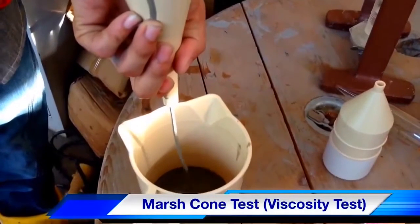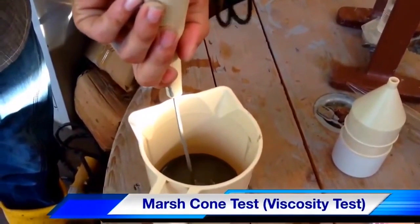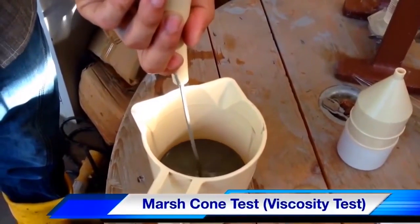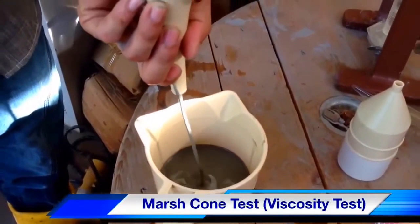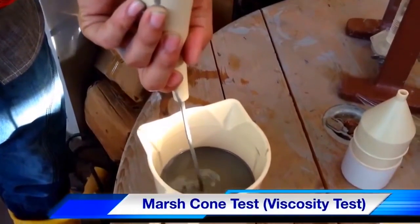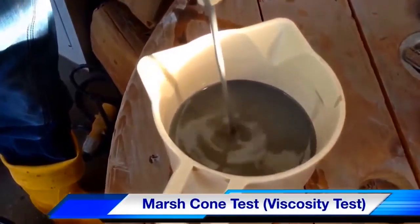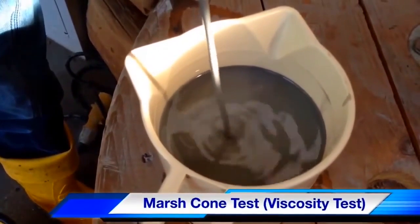Marsh cone method is used to check the viscosity of bentonite. Firstly, the bentonite should be poured into the cone by blocking the bottom of the funnel with a finger. Then the cup is filled by bentonite up to 1000 milliliters, up to the mark. And the time is measured to fill up to the level. Viscosity of bentonite should be between 30 to 90 seconds.